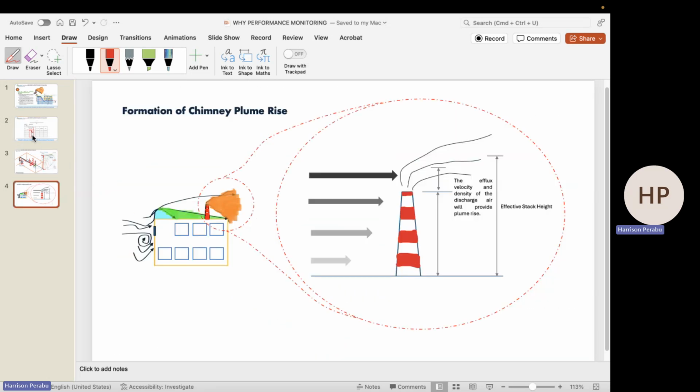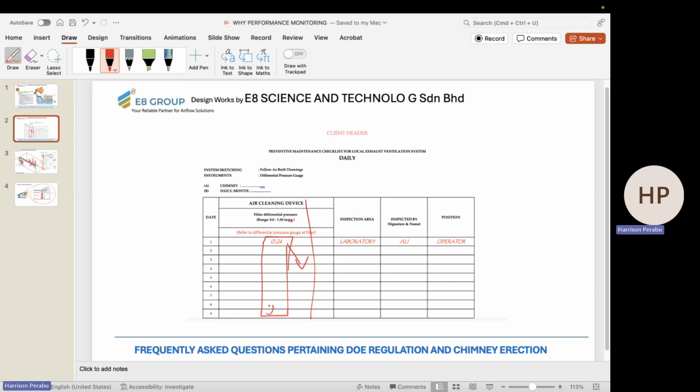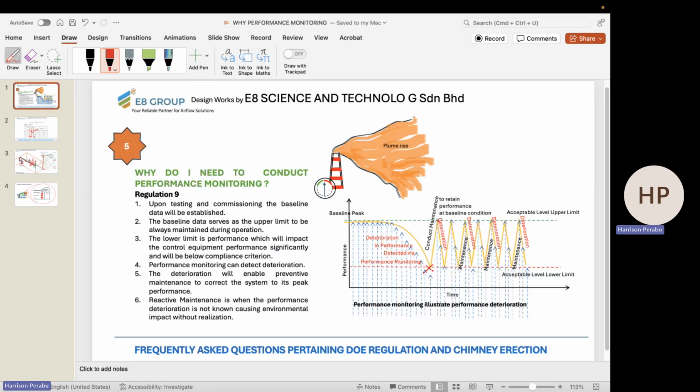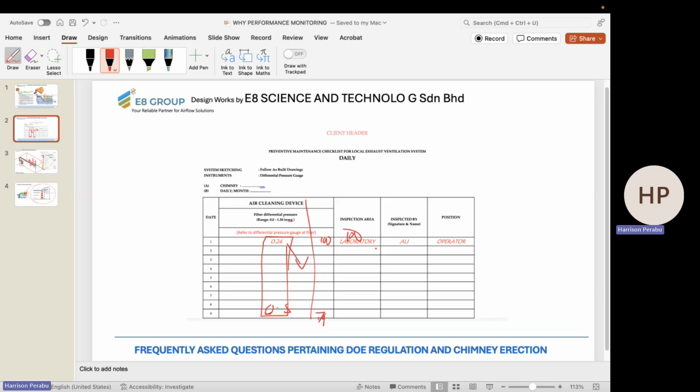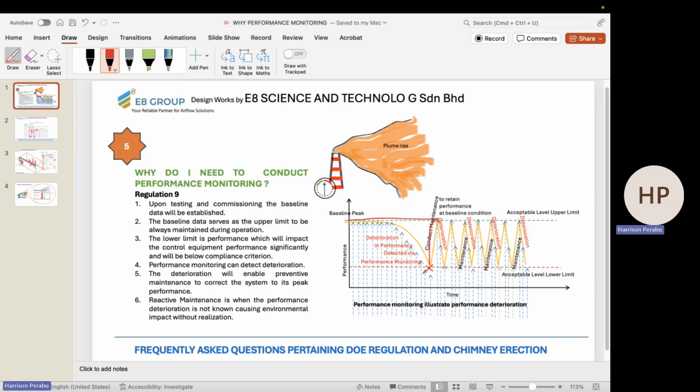So this is correlating. How it works is, assuming that this goes up to 0.5, for instance, at 0.24, you get 100 feet per minute. Okay, anemometer reading 100 feet per minute. But at 0.5, this may go down to 79. So when this goes down to 79, you're going to stop the system and conduct maintenance. When you conduct the maintenance, the condition of the system is going to come back to baseline condition. You keep recording, you keep recording. When you see this deteriorate, then you do maintenance.